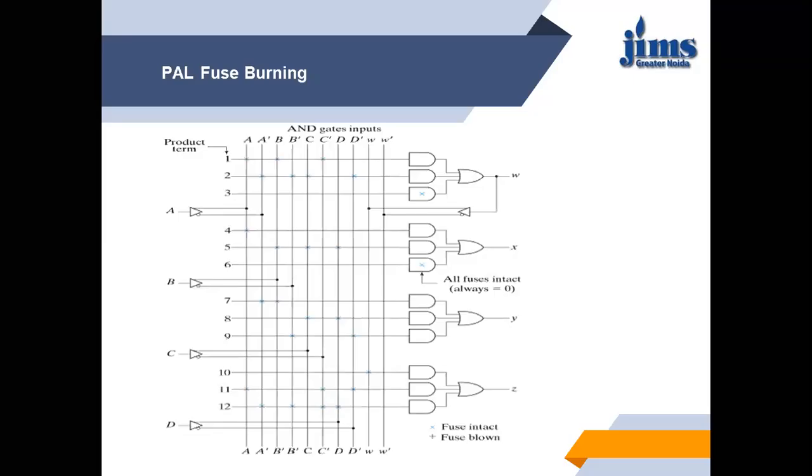But when it comes to the examination, you may stop after completing the programming table. First you will be given the Boolean functions. The Boolean function is minimized with the help of a K-map. Then, after solving the K-map, we have to check whether we can minimize the minterms further, because the number of terms is limited for each OR array. Then we have to make the programming table, and that's enough. We need not draw the circuit diagram.